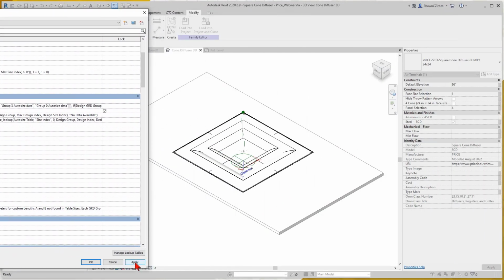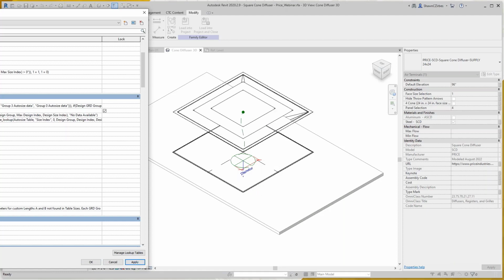And what I want to see is it swap the family that I loaded in just now in place of this family and have no errors and have no major positional changes for this family. I'm just going to hit apply, see what happens. Okay, you'll notice something pretty drastic happened here. It slid from this corner over to here. Now, originally, when I was first looking at this, I thought it actually lifted up in space. That's not what happened. It stayed on the face like it was supposed to, but it slid its origin over to here. That's an issue.